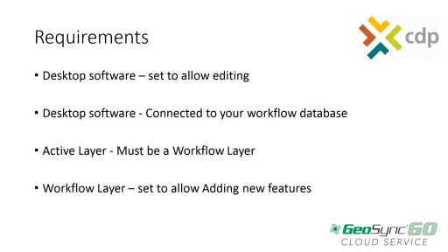The active layer that you're working with has to be a workflow layer. So if you exported data from ArcGIS and you have kind of a static snapshot of your GIS data, you cannot add new points to that. You can only add new data or new points to a workflow layer, which is where the workflow has been designed and set up using the workflow wizard and meets those requirements.